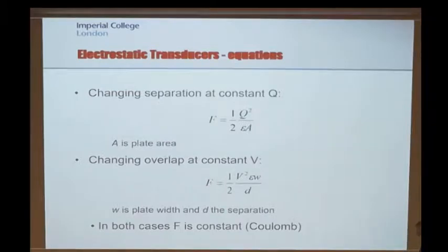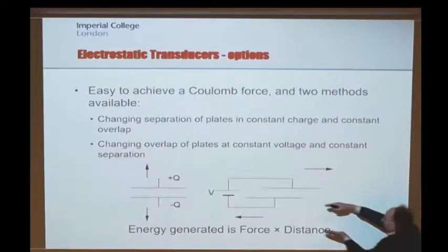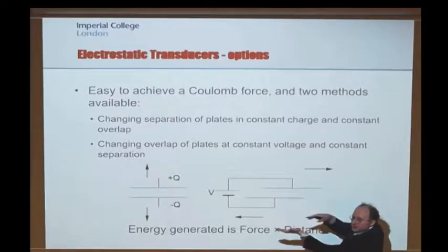So you can calculate that by the principle of virtual work: calculate the energy on the capacitor, and you can then take the derivative in order to calculate the force. And so this is the force calculation in constant charge, so you can see it is completely independent of the separation between the plates. And likewise also for the overlap sliding type approach, it depends on the voltage, depends on a bunch of parameters, but does not depend on how much the plate has slid across itself. It depends on the separation between the plates, but we would try and put this onto some sort of suspension such that the plates were not able to pull themselves together and they could only move in this sort of motion.